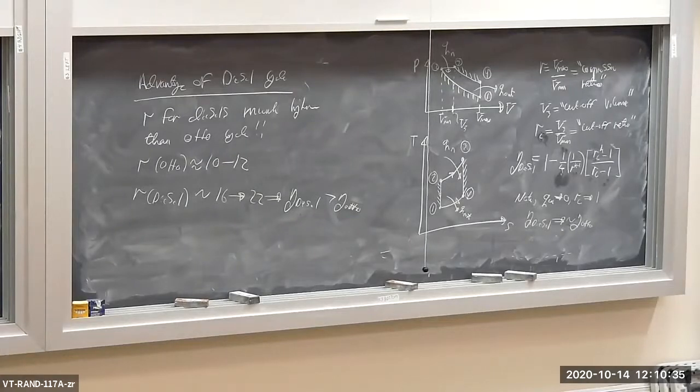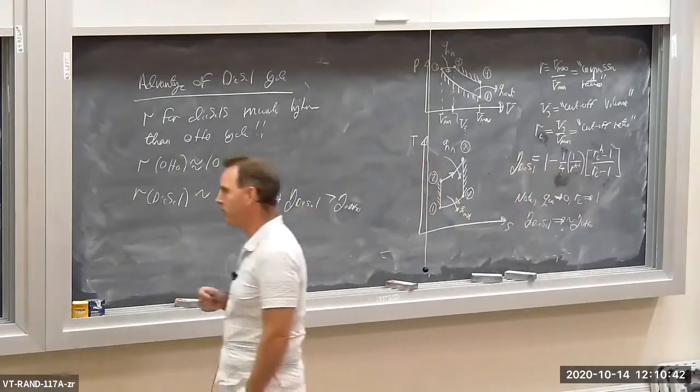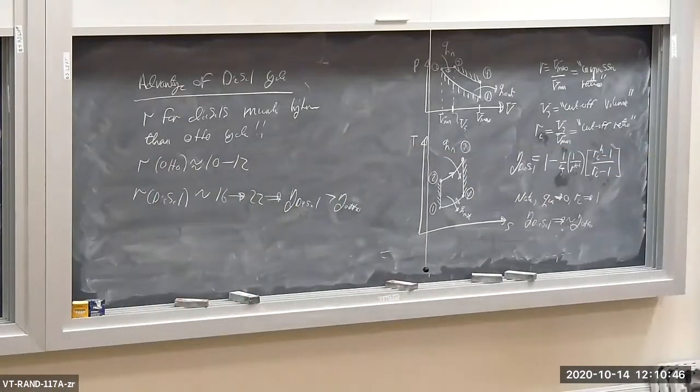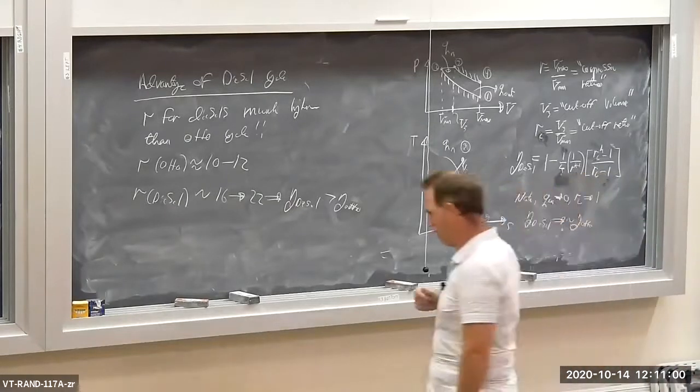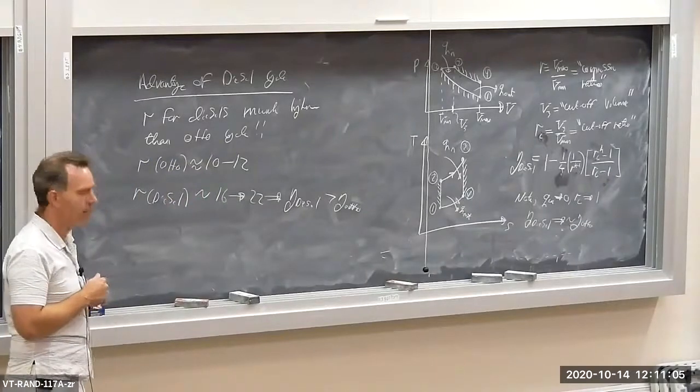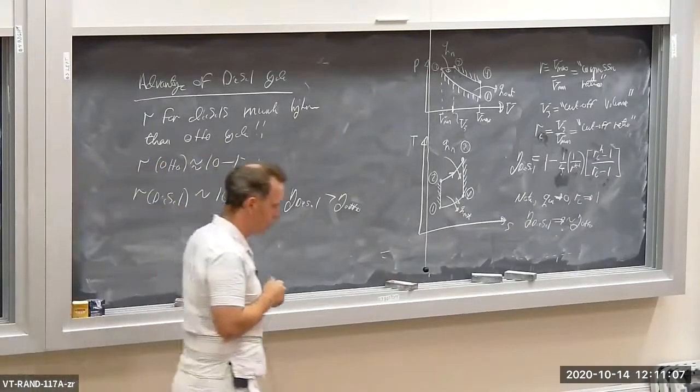Okay, so the primary advantage of the diesel is we can have higher compression ratios and therefore higher thermal efficiencies for the diesel cycle. A good diesel cycle will probably get around 30 to 40% thermal efficiency. A good Otto cycle will probably get around 20 to 30, maybe 30. Those numbers are going up with recent technological advances and the use of direct injection in gasoline engines as well.